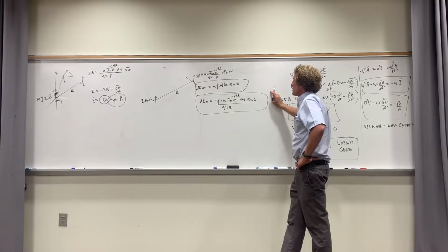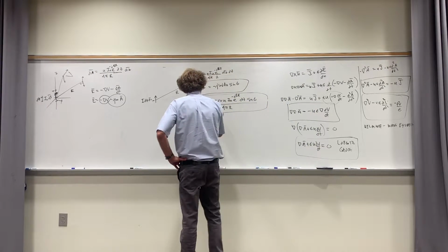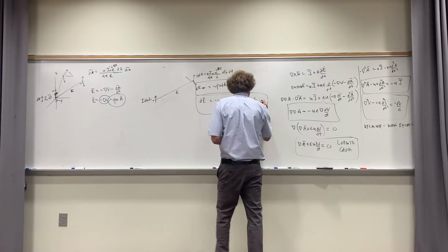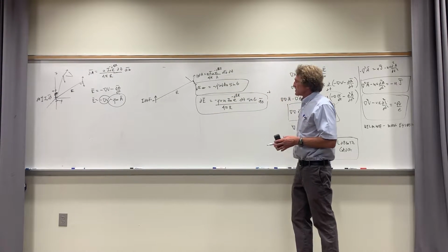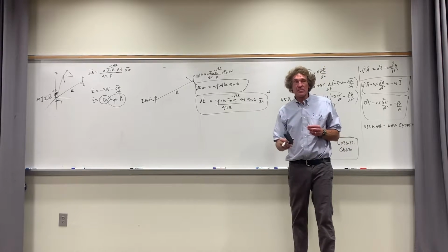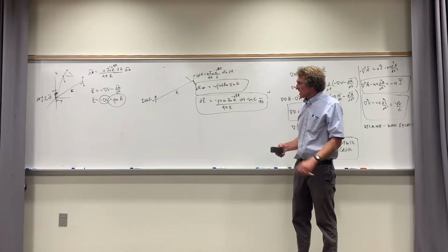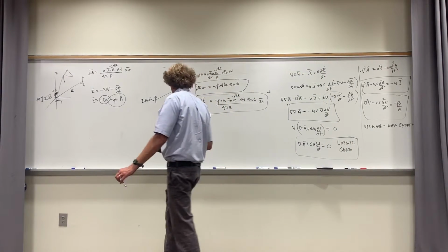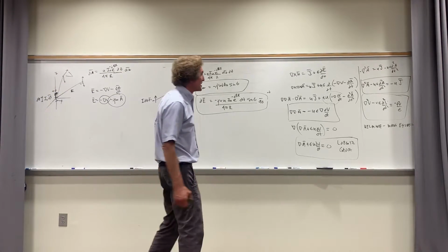So it's minus j omega mu I naught e to the minus j beta r dz, which is the differential length, sine theta over 4 pi r. And if you want the differential E field as a vector, you would just put a theta here. Now, that is real important. This is one you write down. This is the differential electric field from a differential current element in the Z direction. Do you follow me, class? I'm going to show you what he has in his book in 1 second. And I'm going to tell you, you can get that if you want to do the math on this.